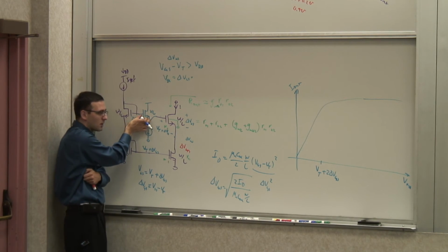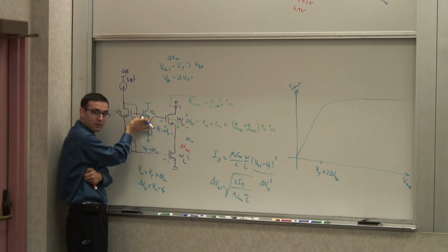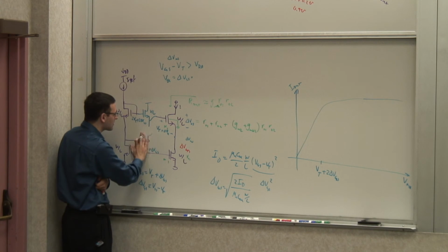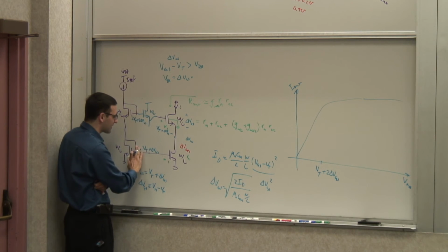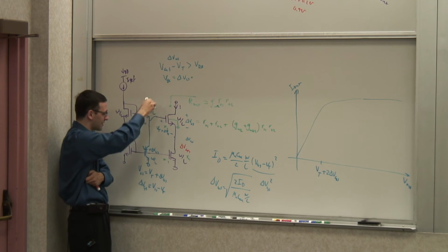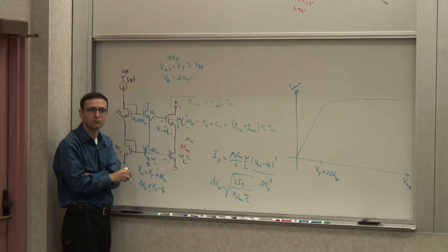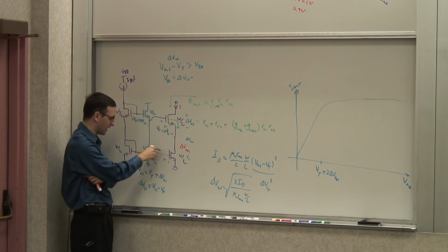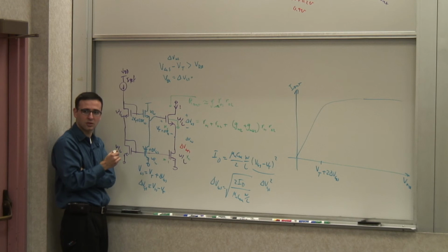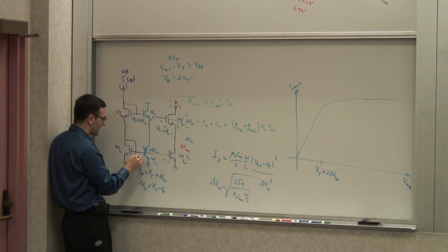Now, what is this voltage drop across here? No, it's more than VT, so it's VGS. It's VT plus delta VGS. Now, let's forget about this current source. I want this to run at the same current, right? So I can actually make this another branch of this guy and make this W over L2. So all of these 3 branches have the same current. Fair? I could do that, right? So this branch and that branch and that branch all have I branch. I'm just kidding, I got rid of that current source so that I made it simple.